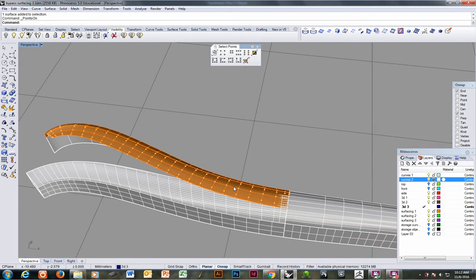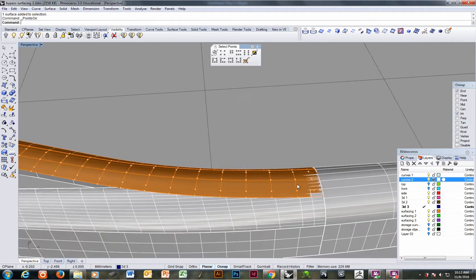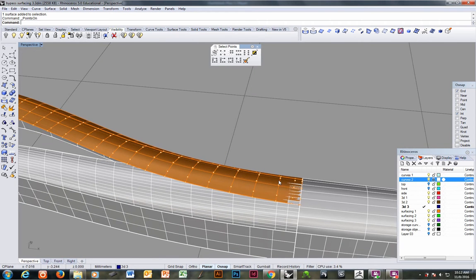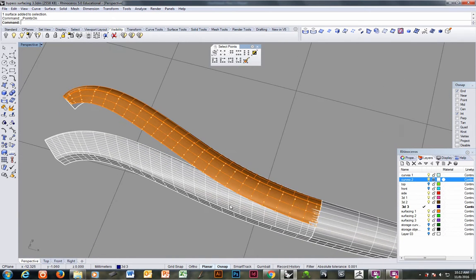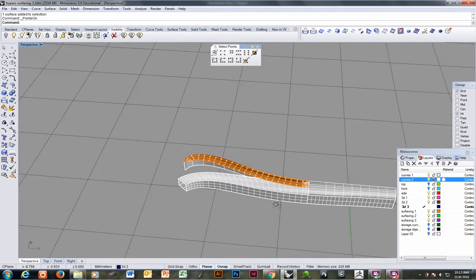What I want to do, class, is I want to gradually start to slope this away from the edge here. I don't want to break the smoothness, so I'm going to leave 3 or 4 points. See, I'm not going to actually intersect this until I get way down here, so I can actually leave quite a bit, depending on when I want that to show up.